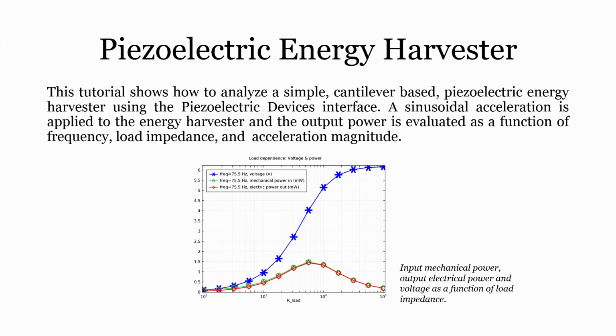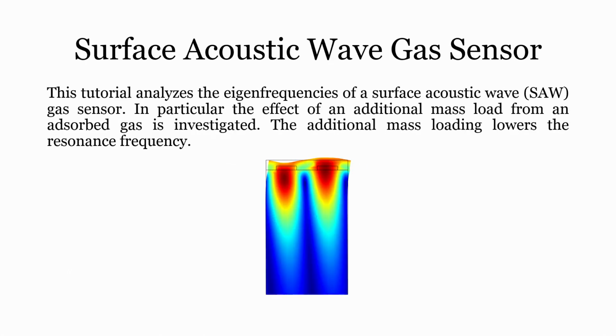It can also be used as an energy harvester, and we will be looking at the tutorial on how to analyze a simple cantilever based piezoelectric energy harvester. Then we will also see a surface acoustic wave gas sensor, in which the tutorial will be analyzing the eigenfrequencies of a surface acoustic wave, that is SAW, gas sensor, and in particular we will see the effect of additional mass load from the absorbed gas.